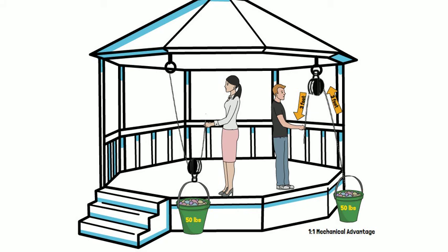If Sandra raises the bucket 6 inches off the ground for every 1 foot she pulls, this means that she will have to pull 6 feet of rope for the bucket to lift 3 feet. Said differently, since the bucket is on both ropes, Sandra will need to take 3 feet out of each rope in order to move the bucket up 3 feet. Since it's all one rope, 3 feet plus 3 feet is 6 feet, and that is what Sandra will need to pull. This is aligned with our 2-to-1 pulley system.